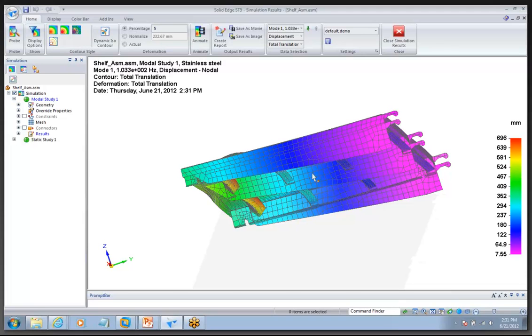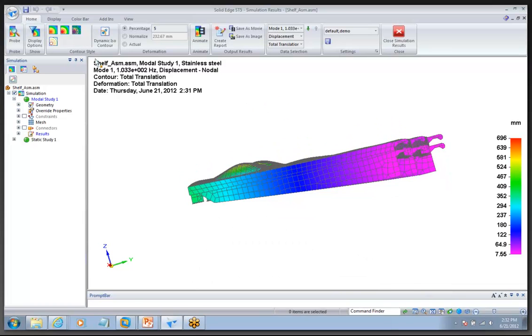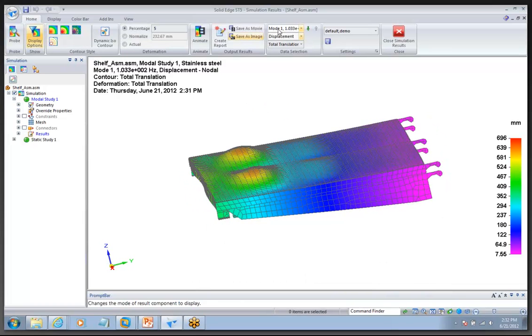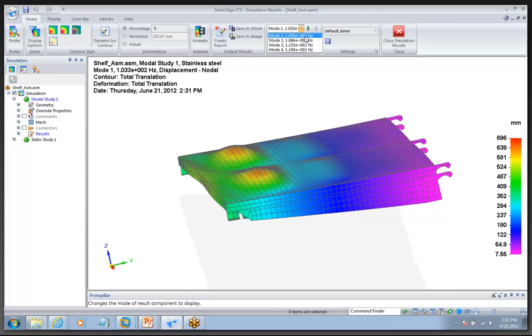So what I did is I added another bracket there, because now it's constrained. So now it's stiffer here because it's constrained here in the middle. And I didn't increase the mass too much, and I actually went to a 20 gauge sheet metal, which means my part is now considerably thinner. My parts are now considerably thinner than they were, so I'm saving in material costs. And if we take a look at this mode, you can see now that the mode is up at 100. So I was able to do that.